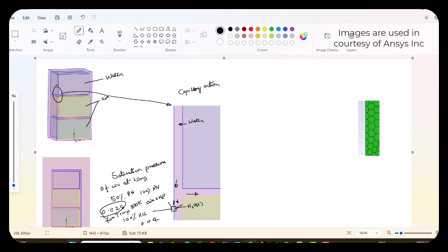So the driving force, mass fractions can be said as partial pressures of water vapor. So I will say the amount of water vapor that would be added from the liquid water to the other side is proportional to the partial pressure at saturation condition, that is at 100% RH, minus the partial pressure currently present in the adjacent cell of the wall.